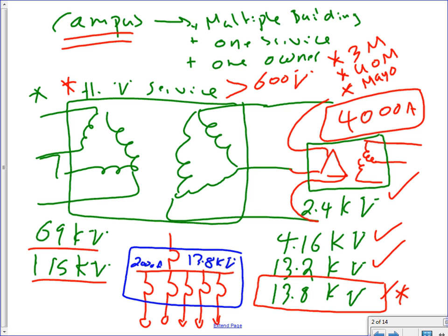It is dangerous. Now if 480 can kill you, this can evaporate you, literally. If you get a short circuit at 13.8, they wouldn't find you to bury you. At 480, they will find you. You will have a proper burial, but at 13.8 switch gear, with an arc flash inside it, you might not be found. Literally, that's how dangerous these voltages are.